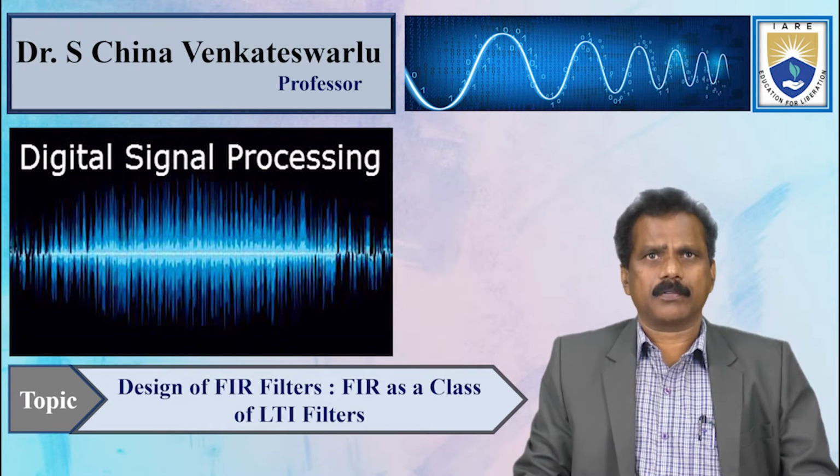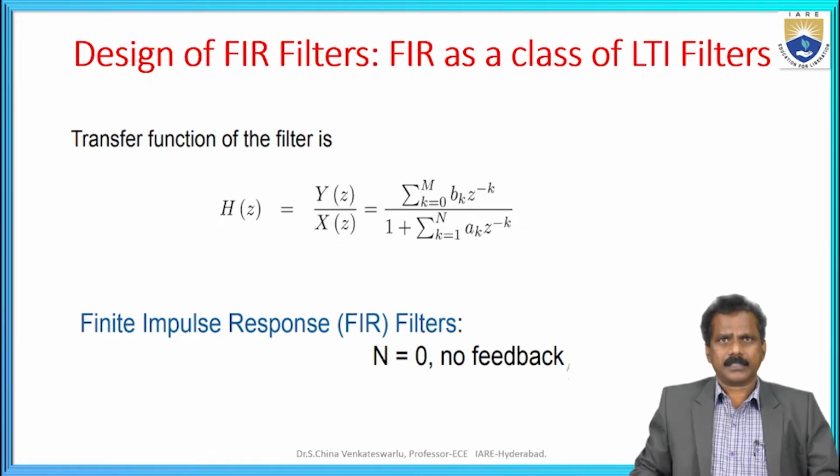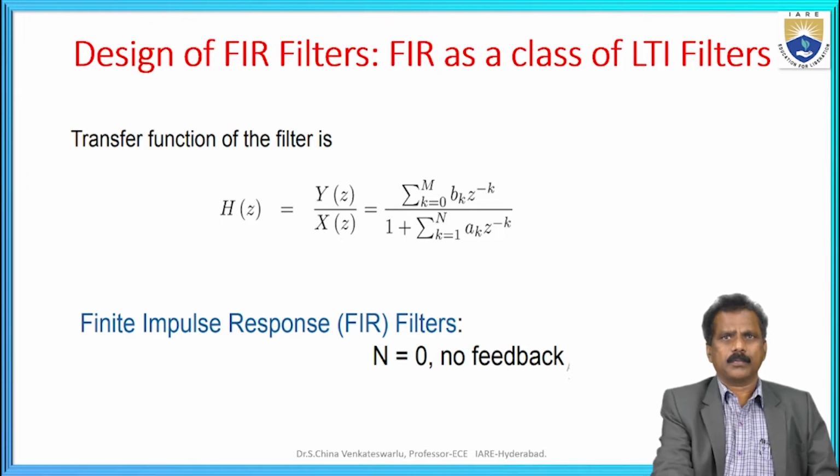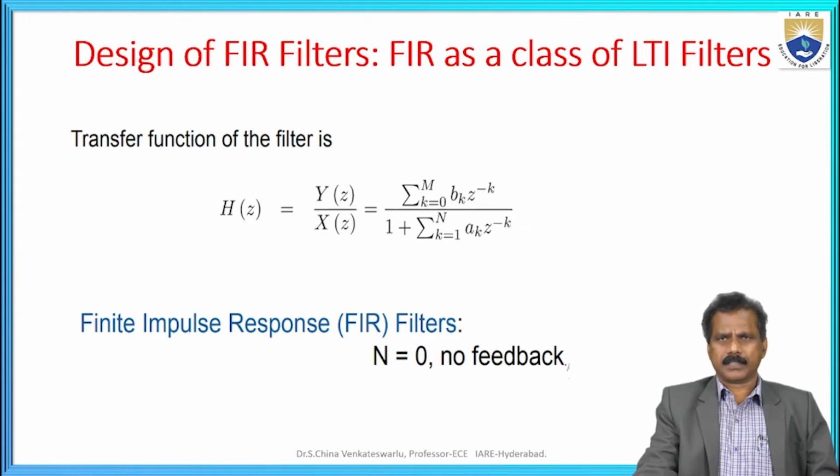Today we're talking about the design of FIR filters, finite impulse response, as a class of linear time invariant filters. In this case, the transfer function of the filter is H(z), where H(z) is equal to Y(z) by X(z). It is also equal to the summation k equal to 0 to capital M of pk z power minus k,